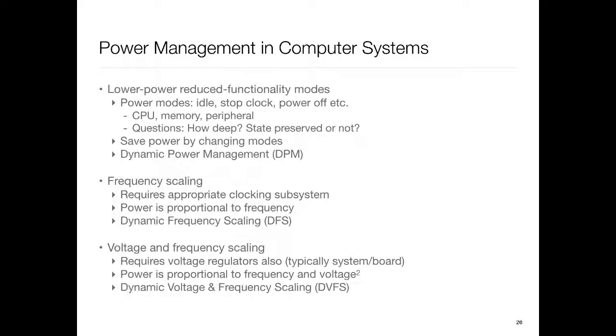With this, if you again take a very simple model that frequency and voltage are proportional, the F max and voltage are proportional, then you can basically say that my power is proportional to frequency cube, and therefore as I lower the frequency, I have a huge gain on the power. So this approach results in improvement in energy for a given computation also, whereas this approach keeps the energy constant. So this is better, but obviously requires more of your system.